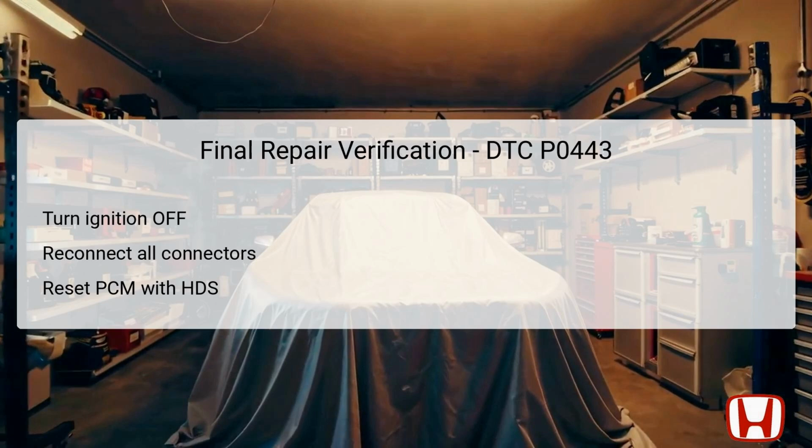Use the Honda Diagnostic System, HDS, to reset the Powertrain Control Module, PCM, ensuring that it has the latest updates and is functioning properly with the new components. Lastly, it is crucial to perform the idle learn procedure for the PCM, which allows it to relearn optimal engine parameters. Finally, monitor the OBD status for DTC P0443, checking for indications of passed, failed, executing, or out of condition. If the test indicates passed, the vehicle's EVAP system repair is confirmed complete.